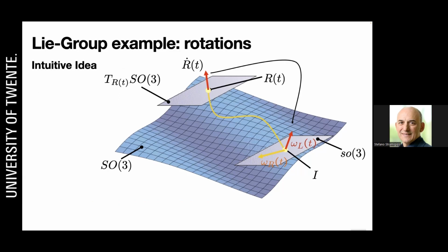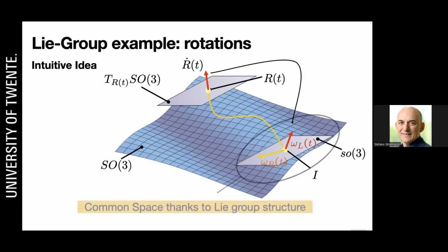And another thing is that you can generalize this to homogeneous matrices. That's a different group. It's called the SE(3) group. But then you see that what is very often used in robotics, what people normally call twist, let's say omega and R dot, you mix two things. The omega is there, the R dot is there of the translation. It's wrong. It's not geometrically consistent. There would be a lot of things to be said about it. I don't have the time to go into it, but at least you have a picture of this stuff.